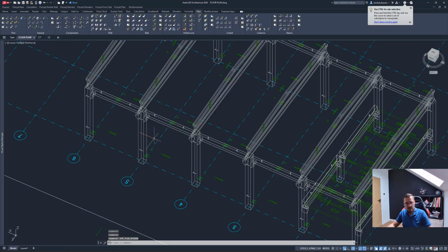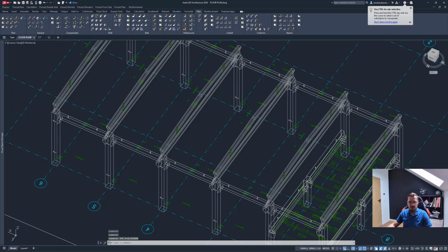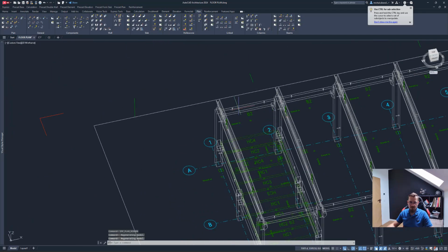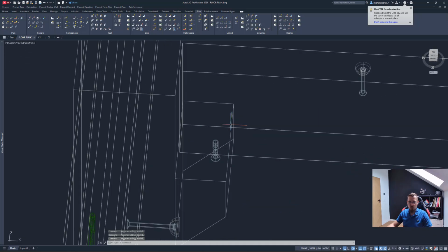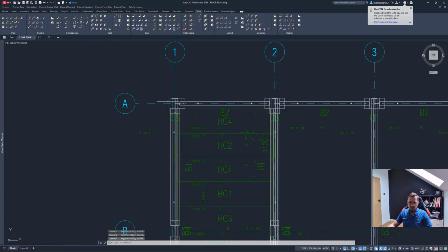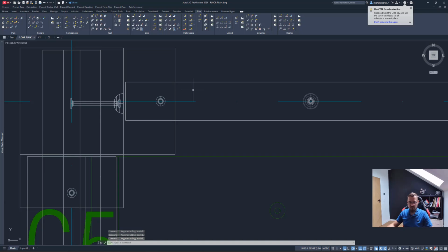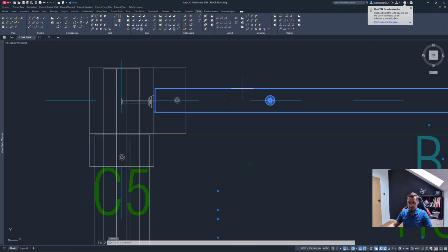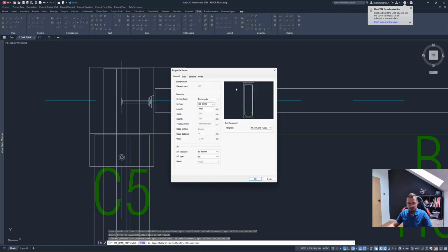One thing that I, unfortunately in the rush and all the emotions, forgot to demonstrate: I want to, for example, create an opening for this lift, so I could possibly connect those elements. So how to do that? Easy, really. Let me select that. This is B2, so once I edit this, all will be edited as well.